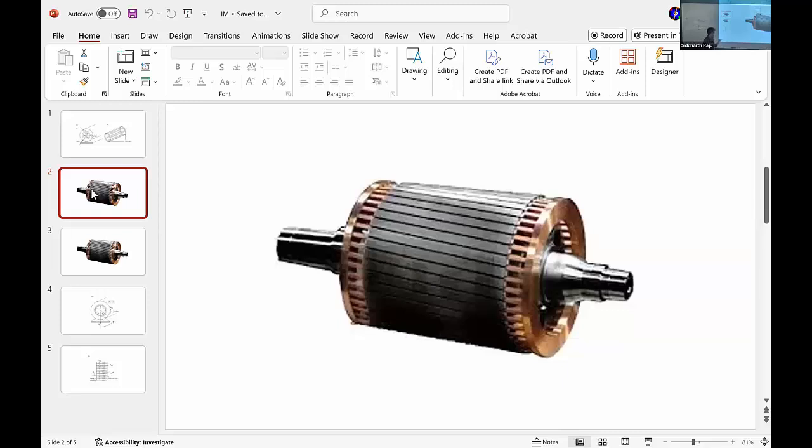For our simplified analysis, we are going to assume the resistance of these end rings that you see there, that's called end rings, is zero. The copper bars going through, we are going to assume they have some resistance, R rotor or whatever. So we are going to assume some finite resistance for the rotor bars, which will be quite small and the currents will be extremely large. But we would assume that the end rings are close to zero resistance and we won't consider it in our analysis, but we can account for that mistake in our assumption towards the end, right?